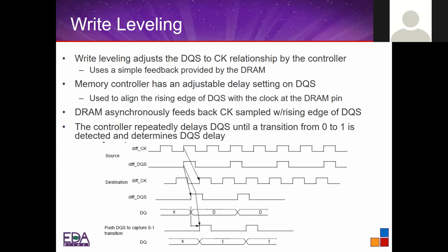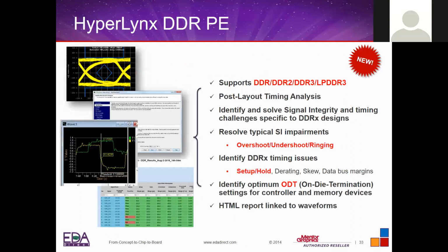No, you assume that this auto calibration does not exist, and then you design your layout to the best that you can. Once you're done with that, now all of these calibration will help you out. Okay, so for that type of DDR analysis, we have this package called DDRC, and that allows you to run DDR2, 3, up to 3. And if you have a need to run DDR4, we have a path to do that.